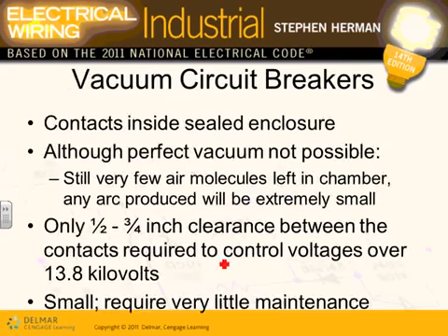The last thing and the most expensive one, guys, and the better one, is called the vacuum circuit breaker. They have a tube like this. They have a process of removing the air from the tube, and inside it they have contacts that they open and close. So when you open and close with no air inside, you have no arc or a very, very limited amount of arc. That's it. If you have no arc, guys, then you can make the circuit breaker interrupt the circuit and live to fight another life.